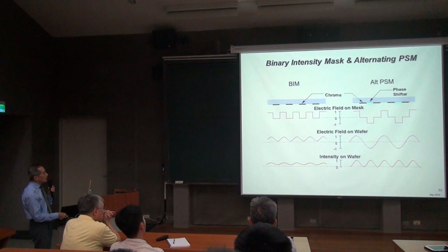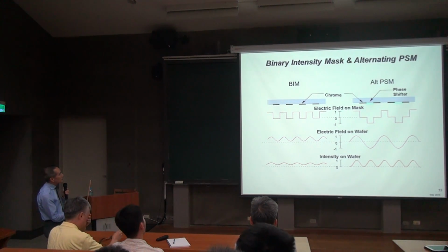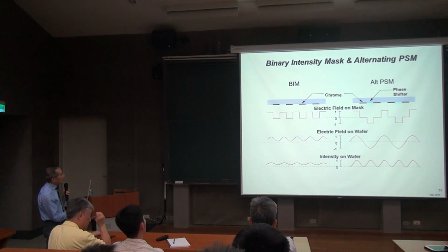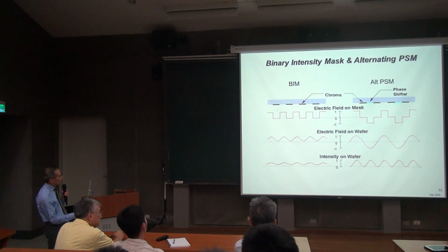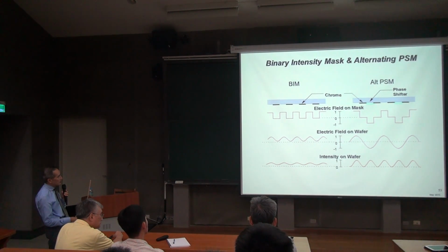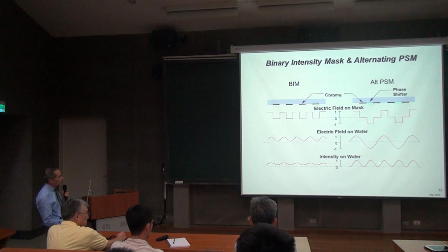Okay? Now, when I have a phase shifting mask, it's changing every other pattern. I shift every other pattern to negative, -1. Positive 1, negative 1. This is 1 and 0, this is 1 and -1. So after it goes through that spatial frequency filter, you end up with this. Again, a single sine wave, and when you square it to get intensity, you get this.